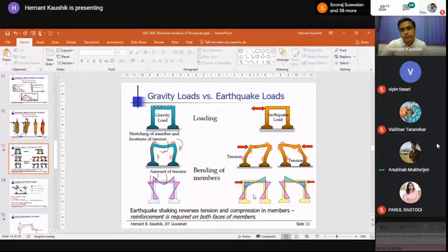And more importantly, here I am not considering the dead load. If I add dead load here, the zero bending moment will not occur at the center of the beam. It will be shifted. And similarly, these will also be shifted when we combine the axial load versus the lateral load.